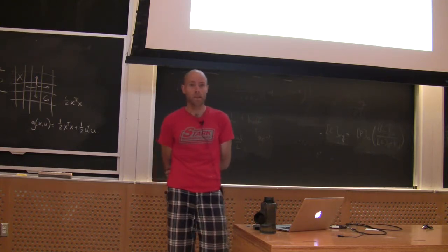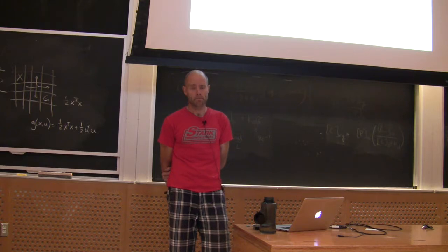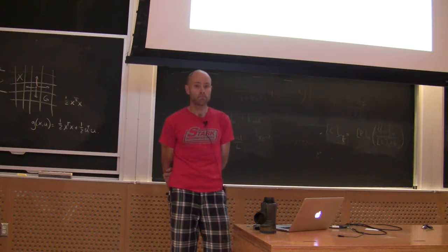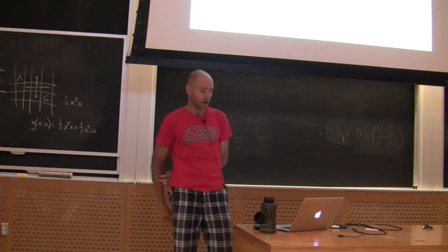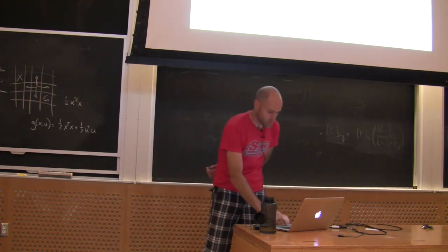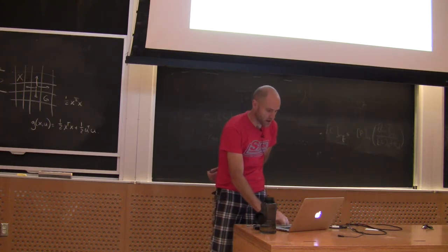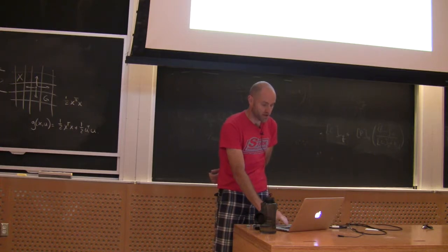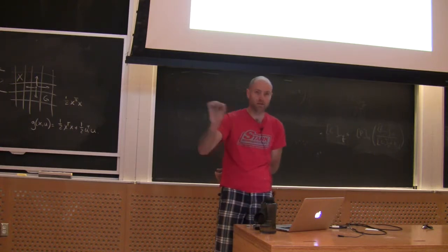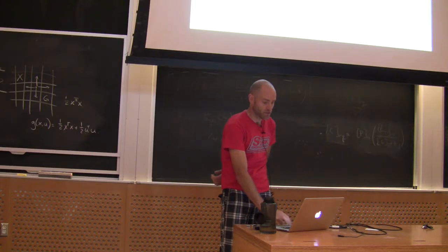So just understand the way to program this: you build up all your states by having some initial condition and applying the dynamics in every possible direction you allow. You solve backwards from the goal. There are two key steps here. This is just the way I've organized the code, but first you discretize your system, you tell it where you want your states to be, and you turn it into a graph problem.